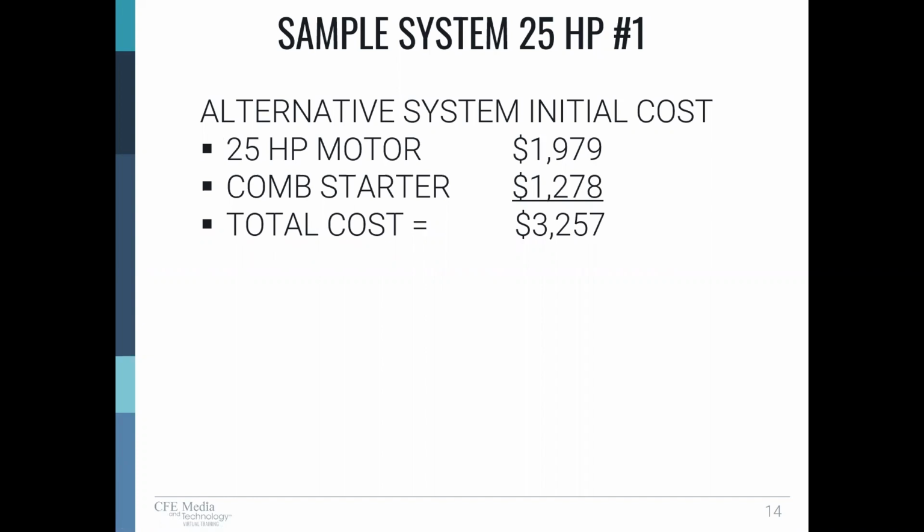Okay, if we reduce the static in the duct system from 6.1 inches of static to 3.3 inches of static, we're able to achieve with this same fan the 30,000 CFM with a 25 horsepower motor. At its operating point, it's operating at 24 horsepower. So that's pretty close. The motor is still operating at 92%. The VF drive is still operating at 97%.